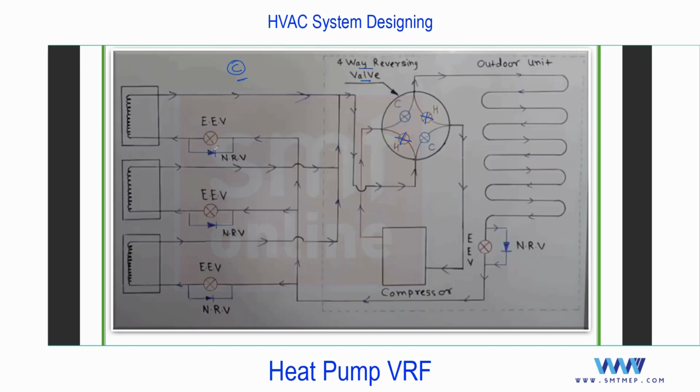And apart from this, for all indoors, you'll find NRV. And I believe you know what NRV is. It's a non-return valve, right? The rest of the thing is the same. So first try to understand this heat pump VRF in cooling mode. As I said, any one mode at a time.